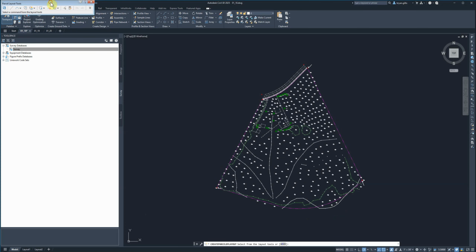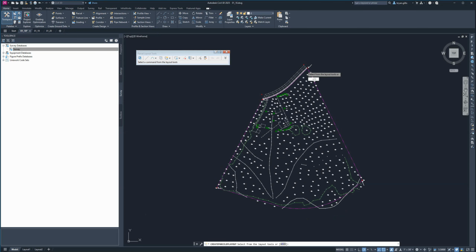You'll have this toolbar open up here. So you'll see right here we have options for manual parcel creation tools. Those are going to be the create parcel, lines, arcs, and draw tangent to tangent with no curve options. And that's going to be everything that you need for manual creation. Now we can review the 3 create tools right here as well if you hit this drop down menu. And then you're going to see we have options for slide lines, to create them, to edit them, to create and edit swing lines, as well as freeform creates.